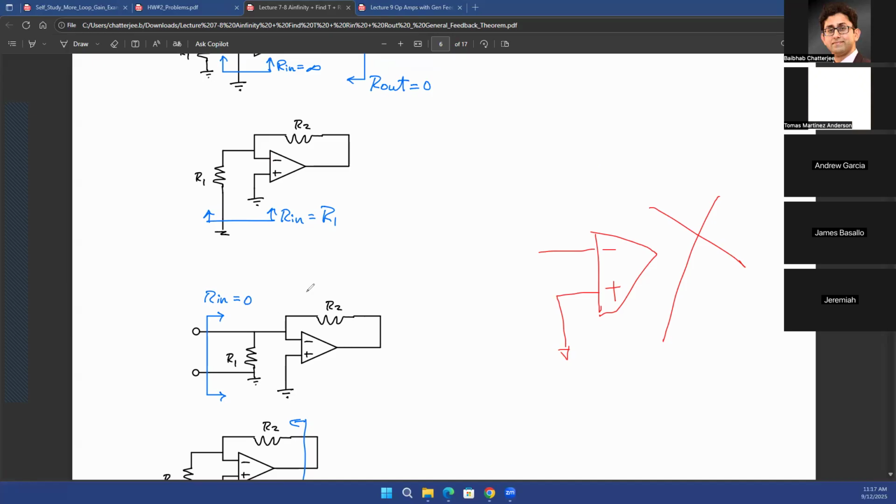What do you mean by any resistive network? Right, on the negative feedback. Yeah, you can have resistive, capacitive, inductive, any kind of negative feedback, or you can have more op-amps. It is a possibility that you have another op-amp in the feedback path. You can do that. We'll look at some of those examples later as well.